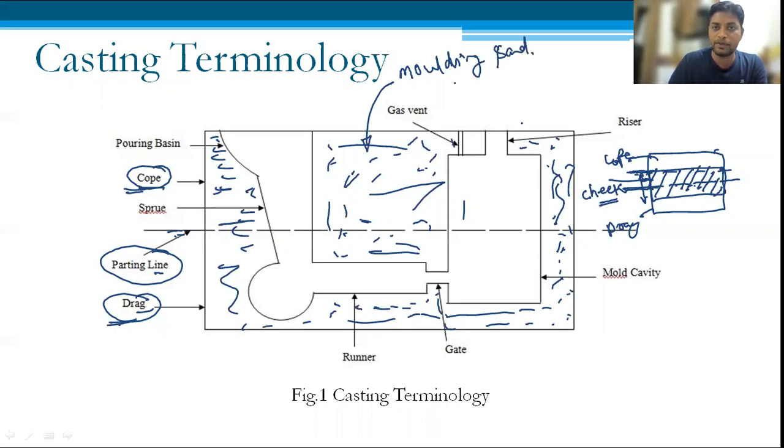If I simply say, it is a combination of, first of all, silica sand, which is vastly available for free. Secondly, we are using clay binders, like kaolinitic clay, which we also call fire clay. Apart from that, bentonitic clay is also available, so we mix that along with it. And sometimes if we need moisture, then we add water into that. So accordingly the properties will change.